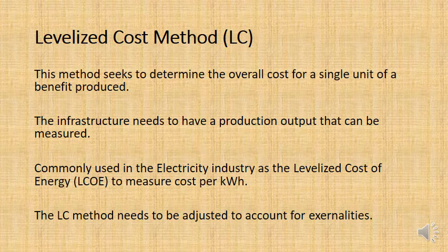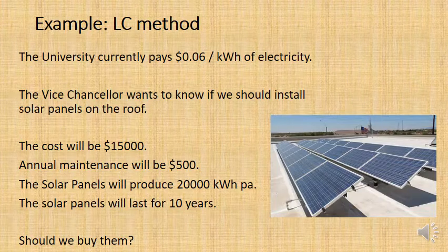Now, generally, with a standard levelized cost method, you are not considering externals. And that's a problem in civil engineering because most of the costs and benefits are external. So you need to value the externalities, which we talked about, and then you need to adjust the levelized cost method. So this is called the adjusted levelized cost method. Let's look at an example of this.